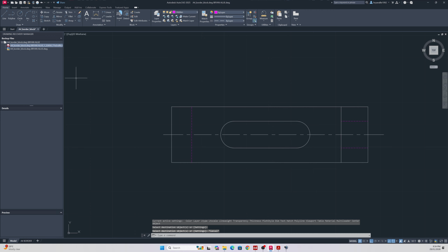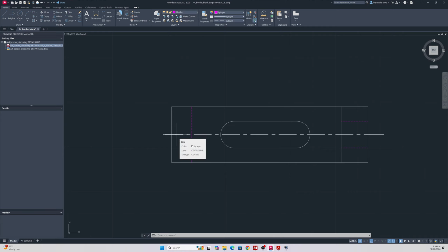Okay, now these are 9, 7 mil. So we need 7 mil from the edge on each side, which is fair enough. So go 7, spacebar, 7, then polyline, go across that, and again that.